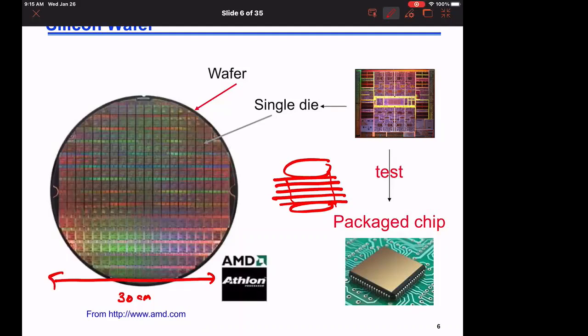And on this wafer, we print many chips. Let us say my chip comprises an inverter. We rely too much in fabrication on parallel processing, so we print many of these inverters. Each of these blocks represents what we call a die. The die is the unpackaged chip. It's the flat design, without pins, without plastic packaging to protect it.